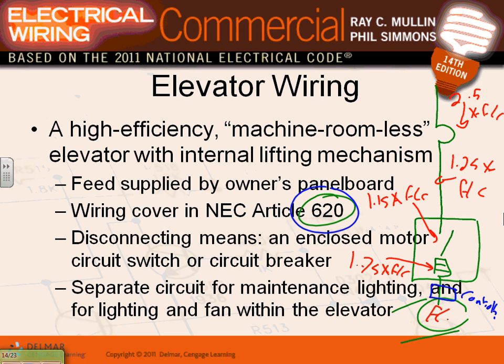A couple of things also you need to know about the elevator, guys. Lighting and fan. Also, the elevator car, they bring a circuit to feed the light and the fan in the elevator car. So in Minnesota, I don't know about other places, and I didn't install a whole lot of elevators, they require you to have an elevator panel, guys, a panel inside the elevator room.